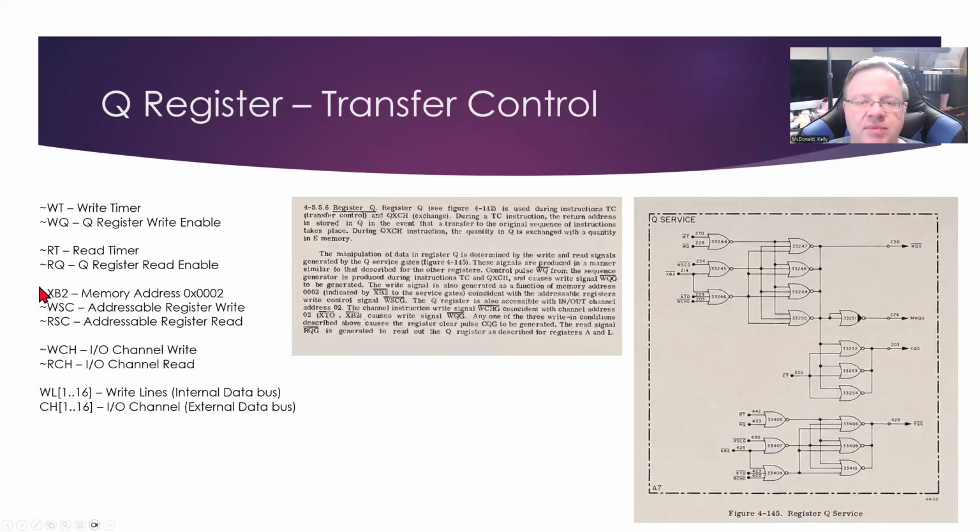And we use the same XB2 memory address in order to signify which register we're going to be writing in and out of, because the L register also uses the channel bus to write data in and out. And then we've got our write lines for our internal data bus, and then our CH or channel, which is our I/O or external bus.